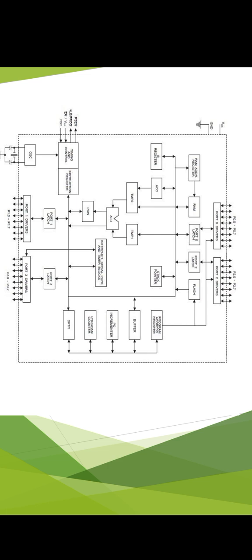Here 4 ports are there. Each port has 8 bits, that is P0.0 to P0.7. These are port drivers and port latches. There are 4 drivers and 4 latches. Then port 0, an 8-bit port, acts as a data bus for I/O in single chip mode and the lower address in expanded mode. Port 2 is an 8-bit port, acts as data bus for input output in single chip mode and the higher order address in expanded mode.